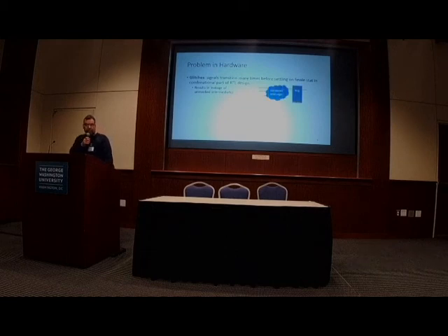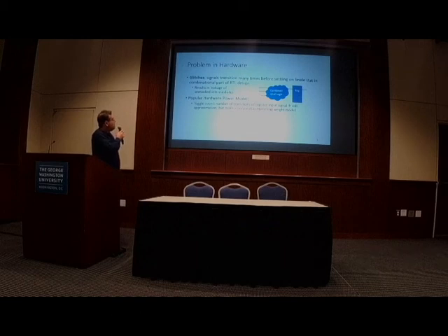Okay. So, problems in hardware: glitches are a major problem. Signal transitions before settling and so on have been known to be leaky forever, since this whole side-channel area started. It results in leakage of unmasked intermediates, so masking is a countermeasure. And of course the power model; there was a little bit of discussion in the first speaker's talk today, right, where you can.